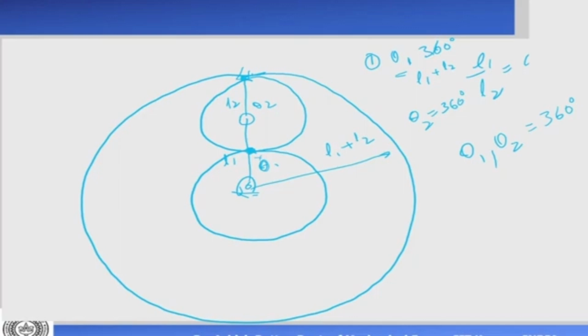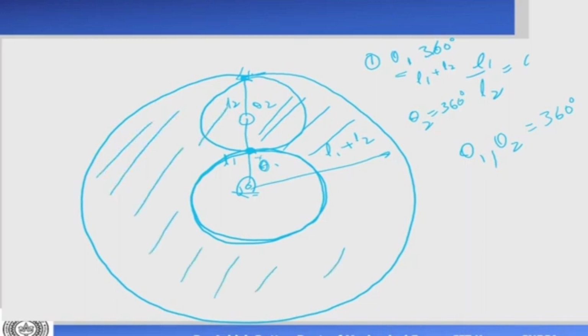Then I rotate theta 1 again, rotating by 360 degrees like this. I get this inner circle. So this is the area, the full area inside which the end effector can go. It cannot go anywhere inside there. So this is the shape of the work area. The end effector can go anywhere inside here, but it cannot go inside there. It's out of reach.